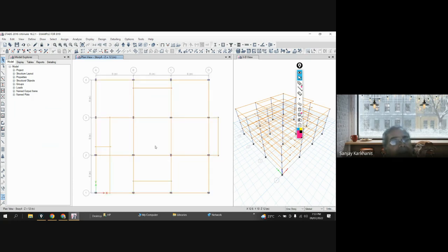So that means you can create a drawing at only one floor, and then either at the time of drawing the beams, you can use the similar option, which is already activated. But if you don't want that, you can create the entire framing on one floor, and you can replicate it on all other floors where your framing is the same. Yes, clear?